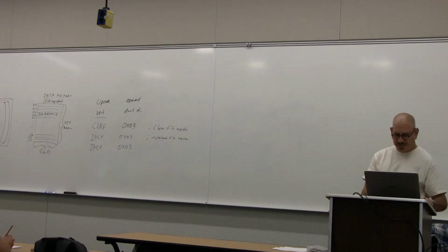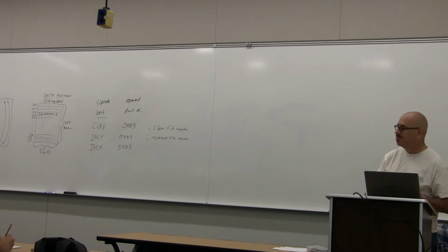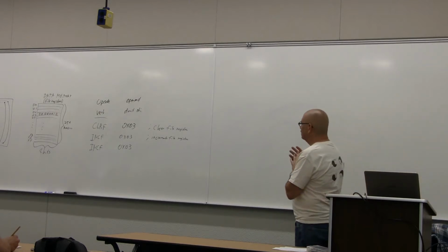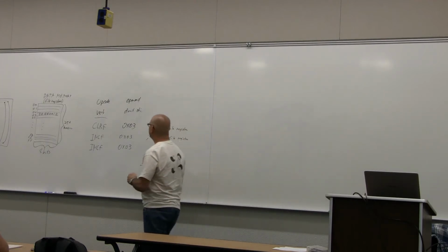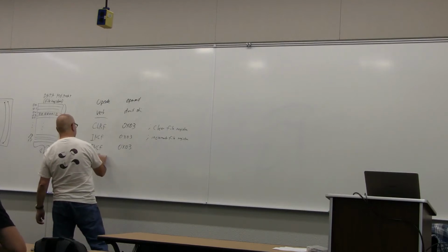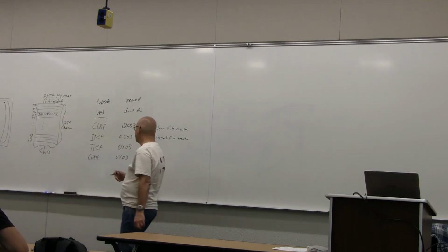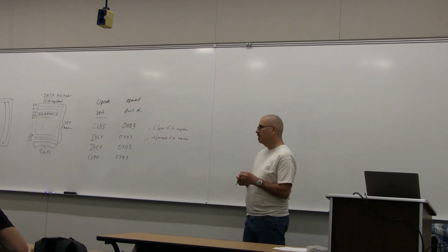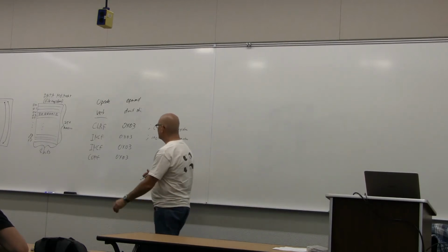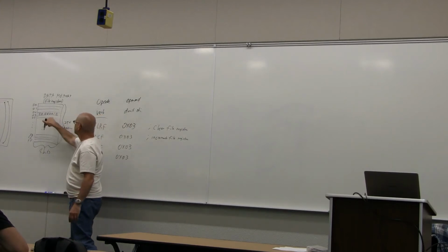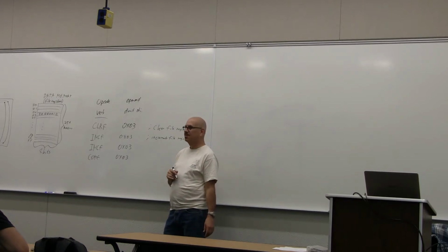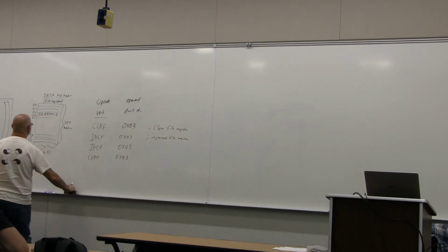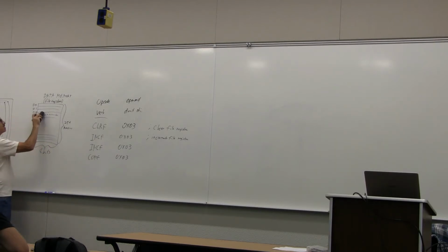All right, so what kinds of instructions can we do? We looked at table 20-1 briefly on Tuesday. Clear, increment, decrement, complement. If I were to say complement file register 3, that means read the current value of this register, which is all zeros except for 1 here. Complement means change your 1s to 0s, change your 0s to 1s, and then write it back. So instead of being all zeros with a 1 in that second position, this becomes this.